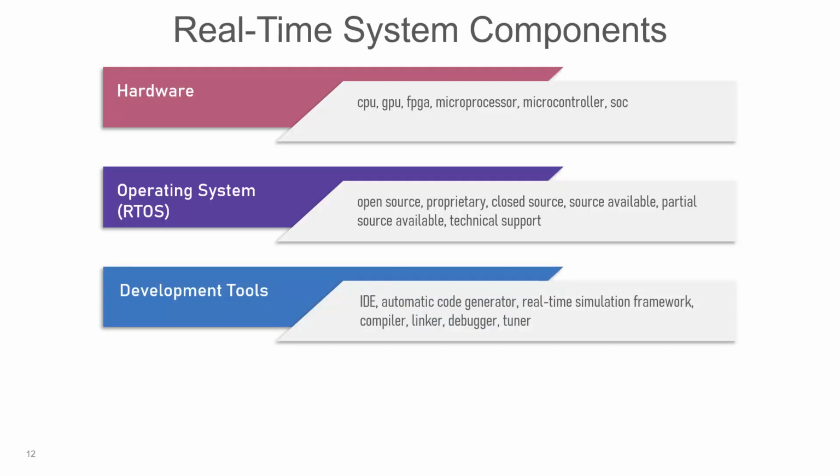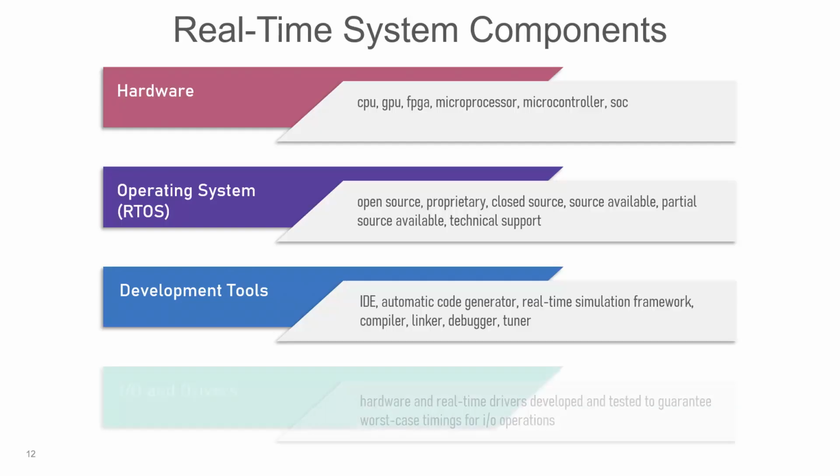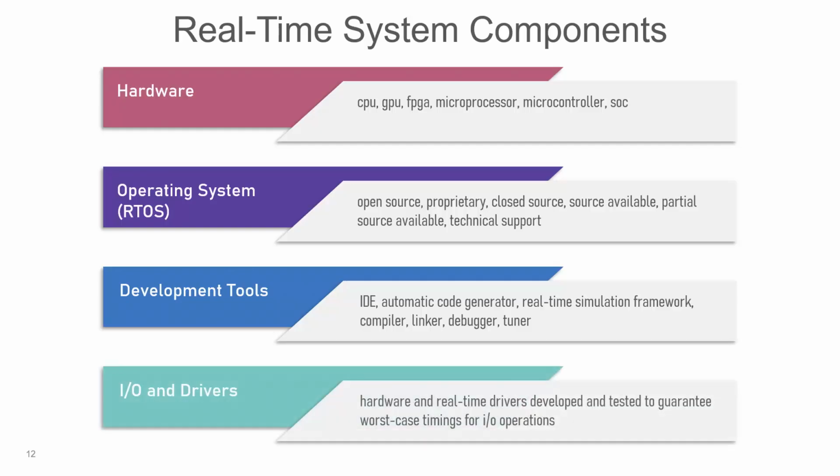Even at this stage, there are a lot of build versus buy solutions. And finally, the decision on the I/O and driver required to talk to the world by meeting hard real-time deadlines. I've worked with I/O cards where it takes more than 60 to 70 microseconds just to read all the analog channels out of the board and get it to the CPU. So if I have a real-time loop of 100 microseconds, then such a card is not a good option because I will only have 30 microseconds remaining for my compute algorithms.